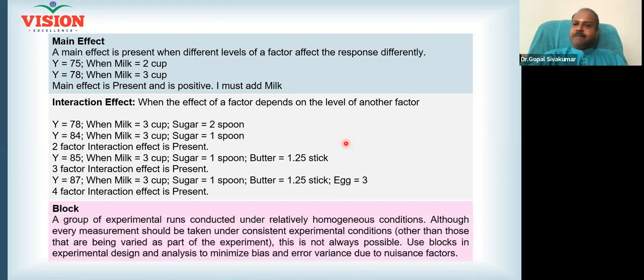So that is why design of experiment is very helpful. But it is a costlier tool. Please understand, it is a costlier tool, time consuming, more effort is required, generally adopted by researchers. If the problem you are addressing really requires DOE, please use it. Just because you have the DOE in your pocket, don't try to explore it. There has to be a clear necessity. Then only you should go for it, right?